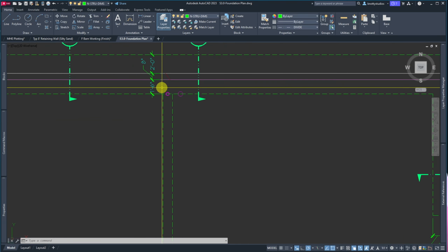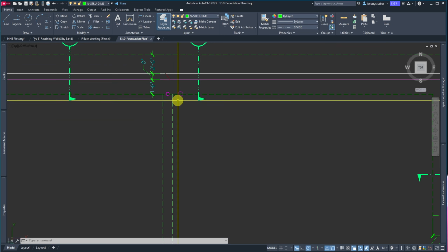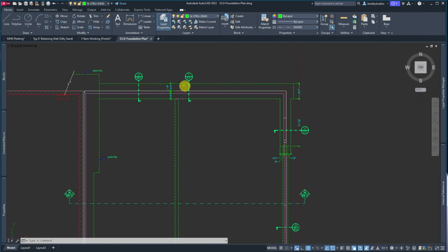So in my foundation plans, there's also any drain or in this case vent location. Those are vents, so they're not going to affect my foundation. I do have a toilet, and no, it's only a toilet on the floor, so I will have a drain for the toilet. That will need to be shown, and it is back in this area. So these are just vents for that, but nonetheless, that is where we are for this lesson.